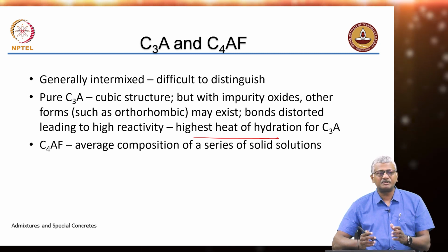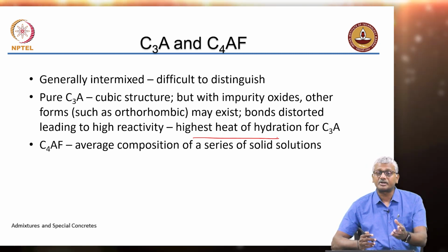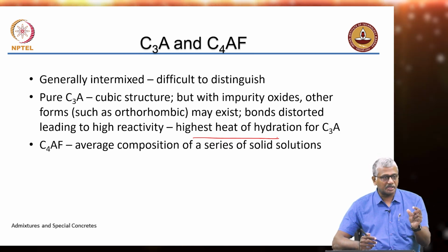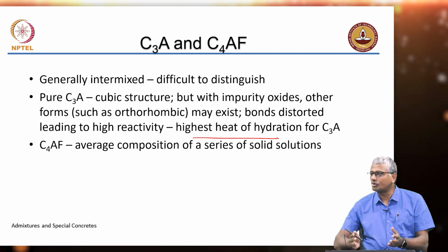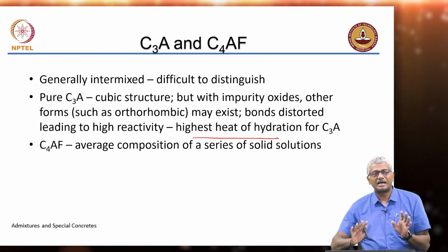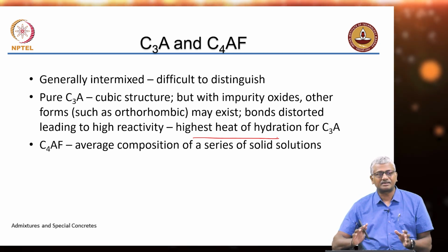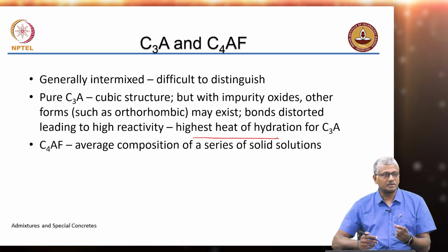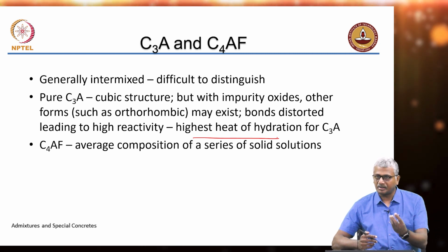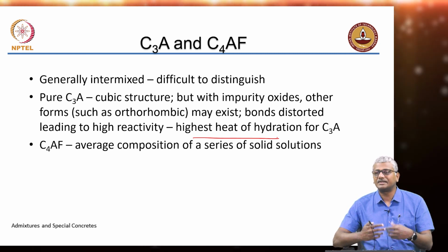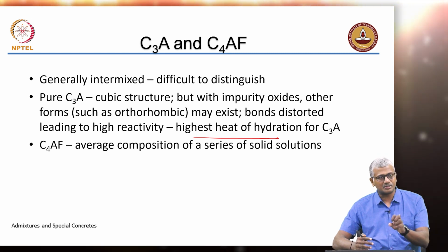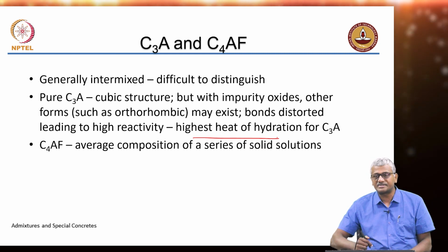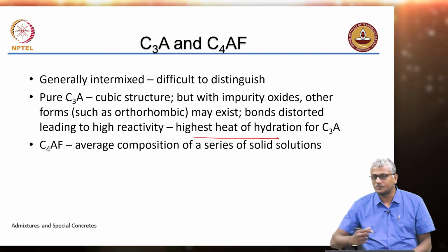If you take a concrete structure which is 50-60 years old, and take a small microscopic image from inside, you will find that much of the C4AF is present as it is in the original cement. It is not reacted at all. That is because iron is present, and this iron makes it highly insoluble. Cement particles have to first start solubilizing and then they react. So, C4AF is a phase that does not solubilize easily. As a result, you will not find the C4AF phases having reacted much even in concrete that is very old.